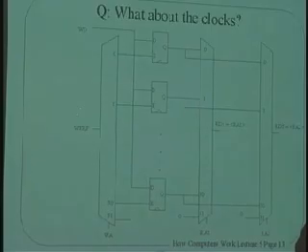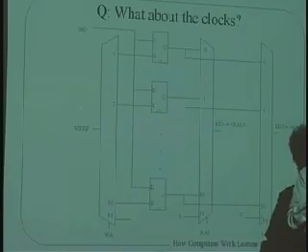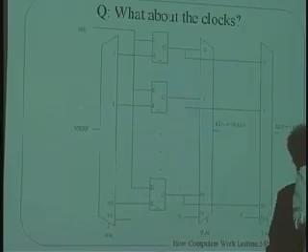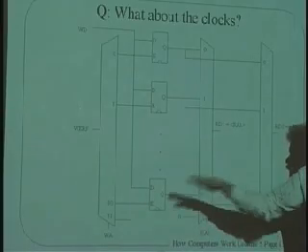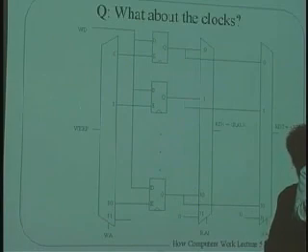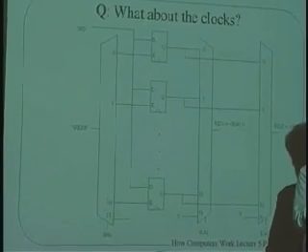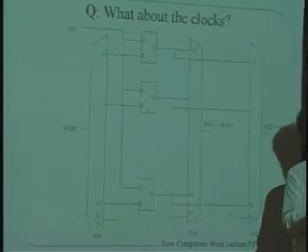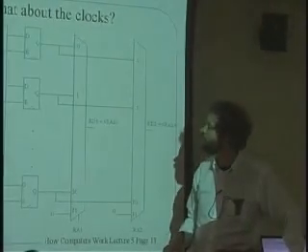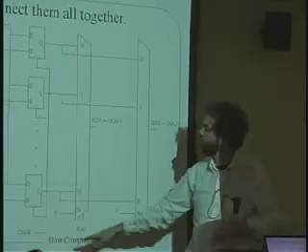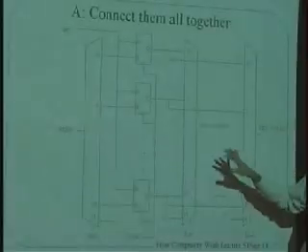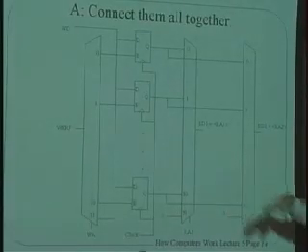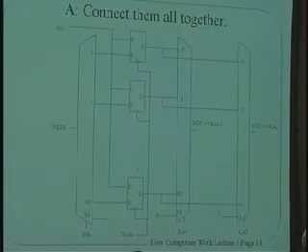Do the easy thing, right? Tie them all together, right? So if there's 10 SLRs here, Phil would hate me for this, you push them all down at the same time. Click, right? But of course, only one of them is turned on, or maybe none of them is turned on. But at most, one of them is turned on. So you go like this, and your finger doesn't work on 9 out of 10 of them, but the 10th one actually takes the picture. So what you do is you hook the clock in parallel up to each and every one of the inputs. And in general, this is the architecture that's used to build that register file. And that's all there is to it.